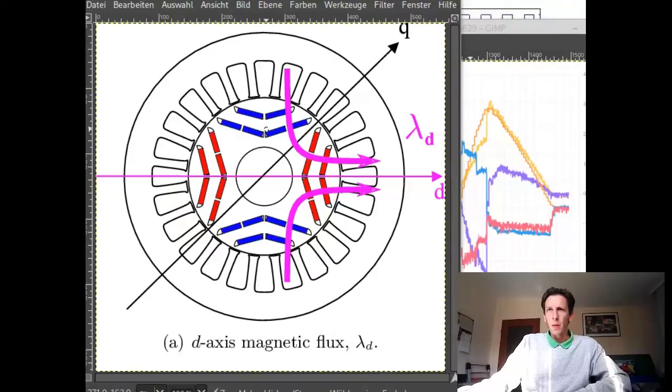Okay, just quick fundamentals of field-oriented control. The basis here is we're looking at a 4-pole rotor now, so every angle has to be multiplied by 2 electrically. So we have the Q-axis. If the rotor magnetic field is here in the Q-axis, it will generate maximum magnetic torque. And then here we have the D-axis. If the rotor magnetic field is at the D-axis, we will not generate any torque at all.